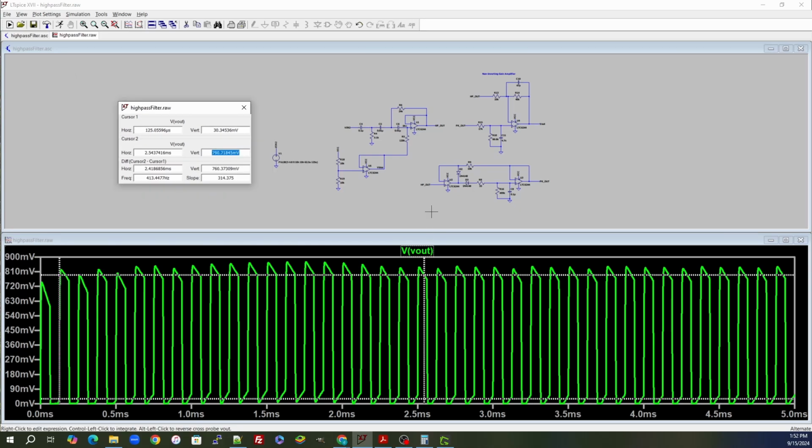So that's how we do it. That's how we're able to take a signal, DC offset it, allow the gain amplification, and be able to detect the entire signal on the output without having to do some really crazy stuff. Well, depends on what you consider crazy, but this is what it is. High pass filter out into a peak voltage detector, and then those two signals feed into a non-inverting gain amplifier with some DC bias.